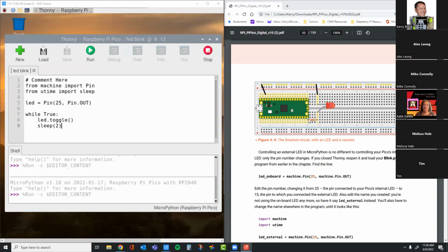This one is pin, what pin is that? 15, right? So pin 15 is this one right here. So we're using the resistor to do the connection here, and then through the LED, and then from here to ground. Okay, so instead of using two wires, I'm going to use a single wire from here to here. And then I'll use this resistor from here to here in the LED. Okay, so I need to grab those out.